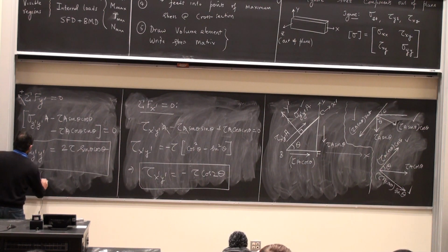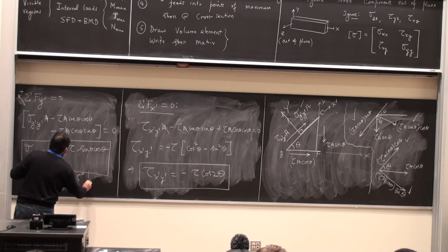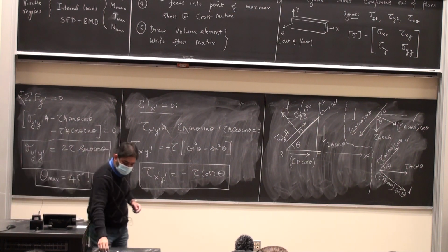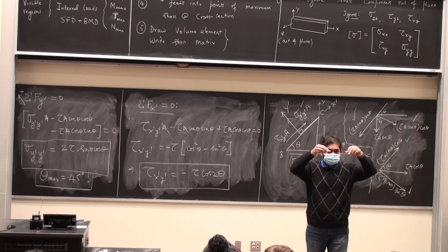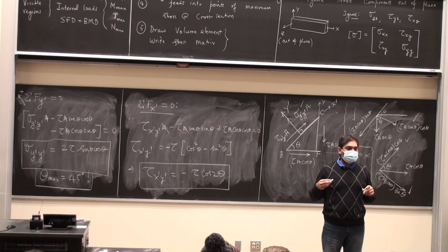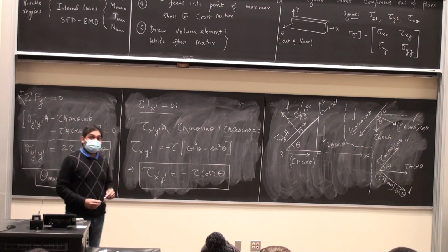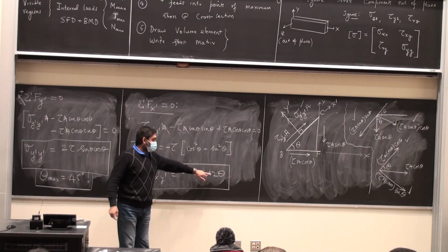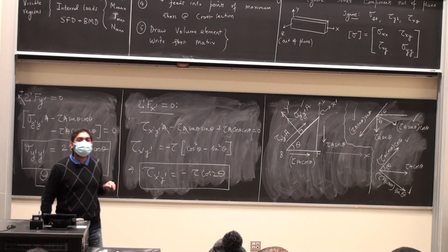So theta max is 45 degrees, which is why you see that when I take a piece of chalk and break it open, I'm just breaking chalks here, you'll see that the angle is 45 degrees. It's no coincidence. The math works out, the experiments work out as well. Observations, predictions, everything. But importantly, look at this. If this is 45 degrees, cosine of 2 times 45 is cosine of 90, it is 0.